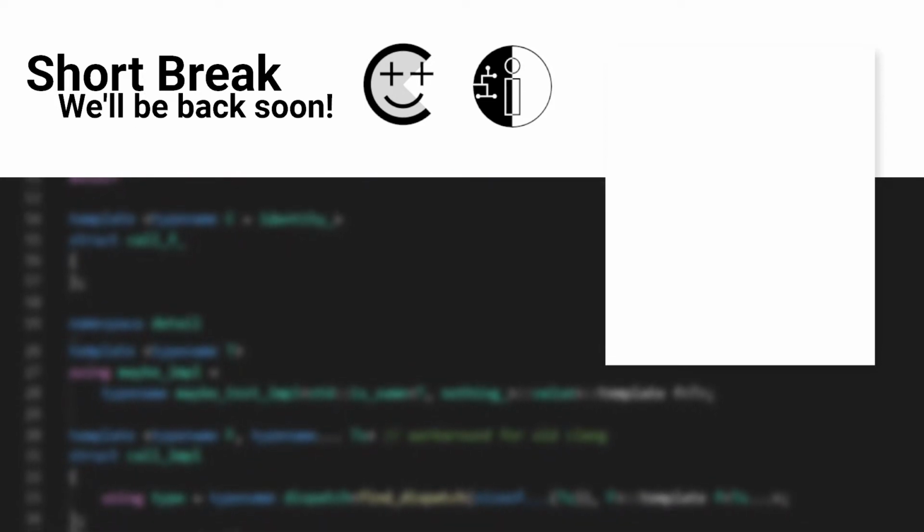And last year we looked at how it works on the NRF51 development board. And there, the debug protection actually does not completely disable the debug port. Instead, it shuts down the access of the debugger to the ROM itself. This means you can still read RAM, you can read registers, you can even control execution, but you can't read the ROM contents, which is what you actually want.